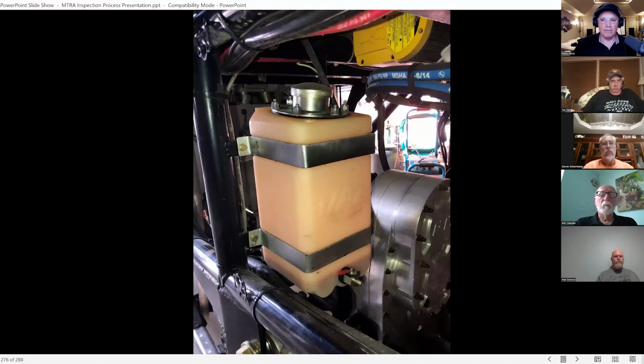This is another one that no one ever thought about, but it has become an issue now because we are doing so much more with the trucks. You're doing these stoppies and different things. Transmission overflow lines: we used to just let them hang and they'd dump transmission fluid on the ground periodically. Of course, as we become more environmentally conscious, we don't want oil on the concrete, especially at indoor shows. But beyond that, now these things are starting to become fire hazards. We don't want trucks doing these type of performances.